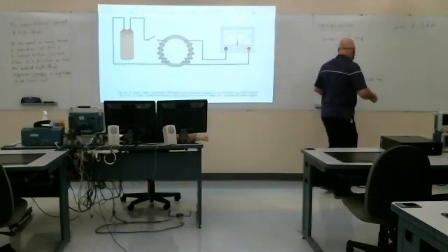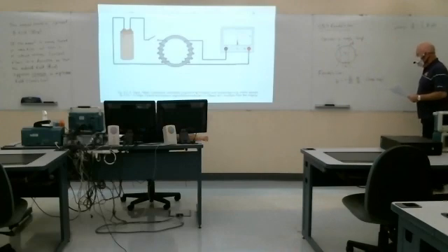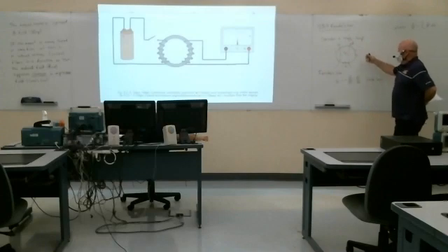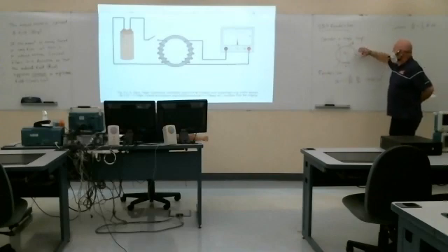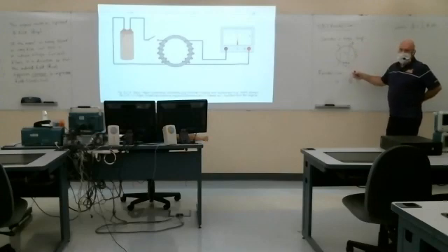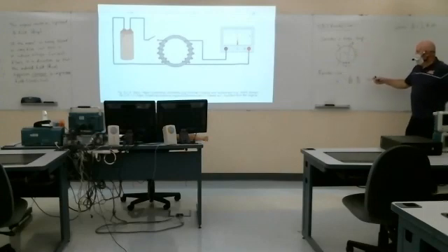And the negative sign here in the equation captures the fact that, let me see if I can get this right. So let's talk about a constant loop area. If my B field is increasing, so my flux is increasing, my induced B field would have to be opposing that. So let's say my B field is Z directed. My induced B field would have to be negative Z direction, which would correspond to a current flowing in the opposite direction, which would produce a negative voltage. Okay. So if the flux is increasing, VT would be negative. That's what the minus sign tells me.